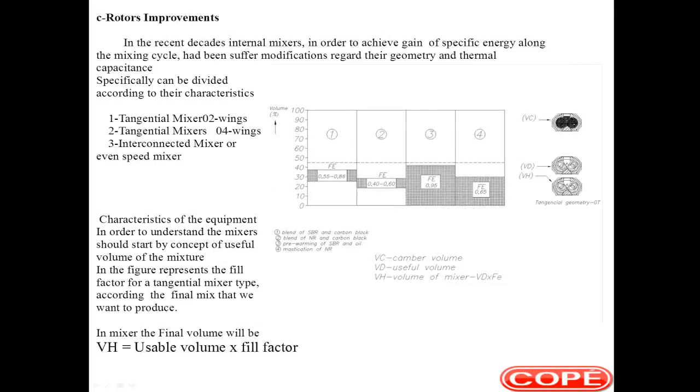In recent decades, rotor geometry and thermal capacity of the mixers have received attention. The rotors can be divided according to their characteristics: tangential mixer 2 wings, tangential mixer 4 wings, tangential mixer 6 wings, interconnected mixer or even speed. Another important